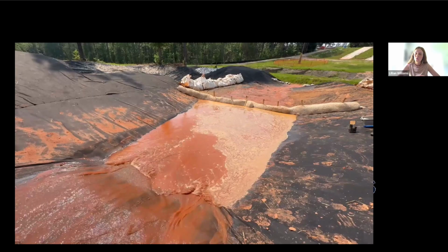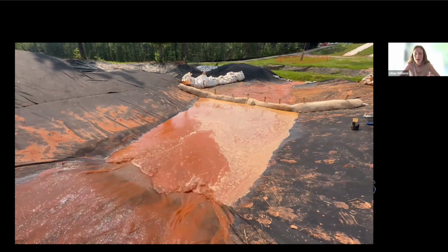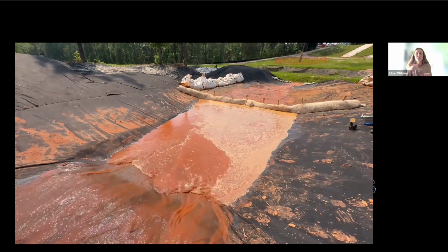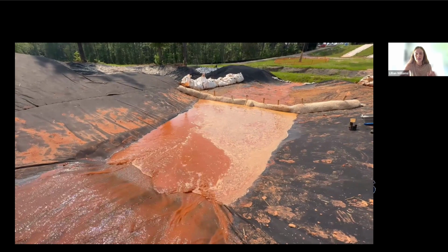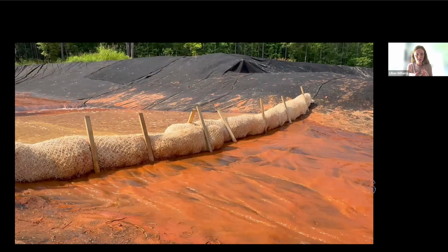So you can see that the wattle is installed as a ditch check. It's spaced-out stapling, so it has stapling alternating in the front and back to keep that wattle connected to the ground. And then we used a non-destructive TP stapling. So here you can see it never goes through the wattle itself.